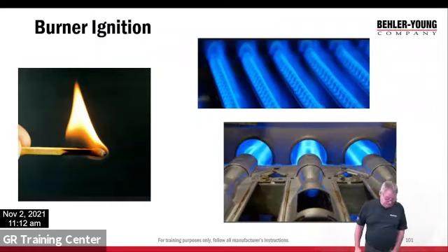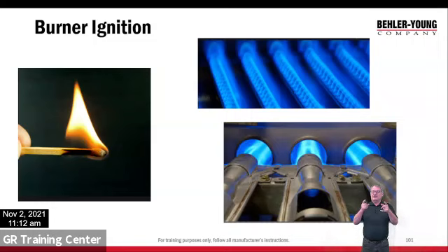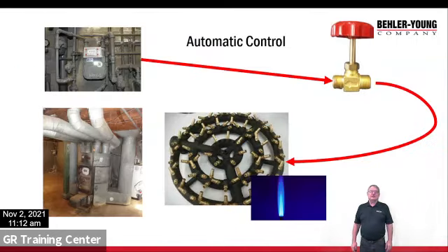All right, so there's the heat exchanger, the advancement of the furnaces. Okay, so now let's take a look at how we make all this work. So above me again is the in-shot burners. That's modern draft induced furnaces. Above that is the old ribbon style burner that went into the heat exchanger for the old gravity vent.